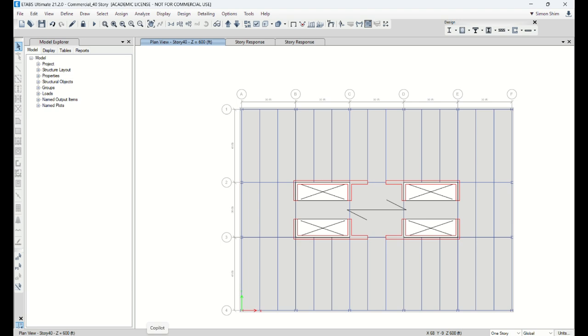Now, the associated overturning moment is obviously the same trend, right? Because the lateral effect in the Y direction is much bigger, the overturning moment about global X is much bigger than about Y. That is just by looking at your building geometry. That is common sense, but you need engineering sense too, right? Secondly, looking at your overall core wall layout, which is stronger, X direction or Y direction, stiffer?